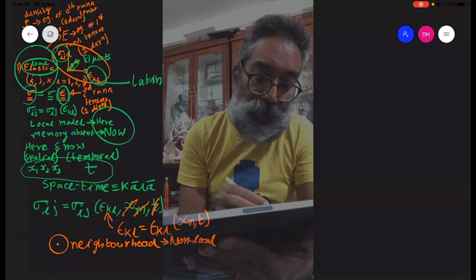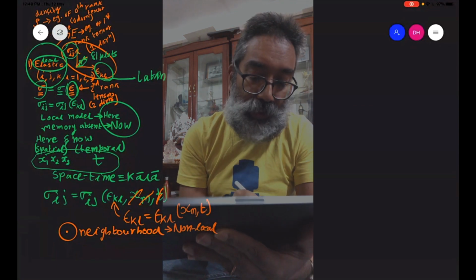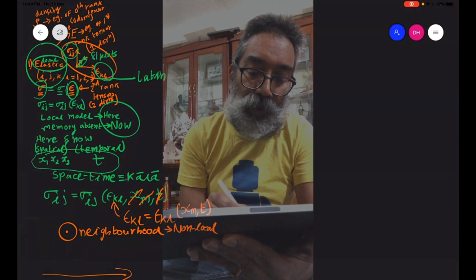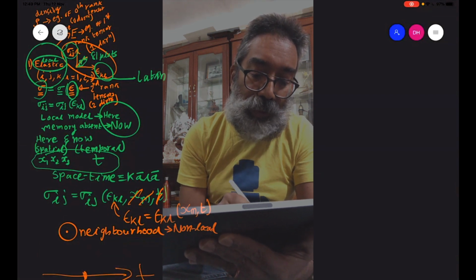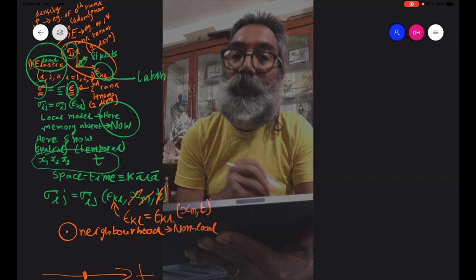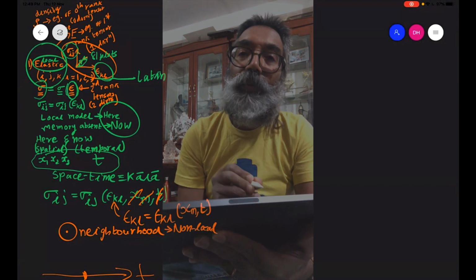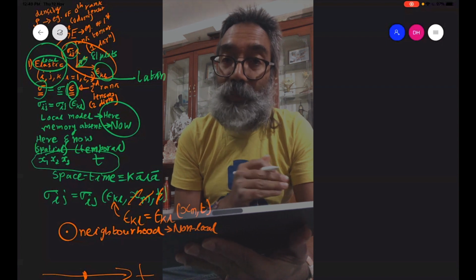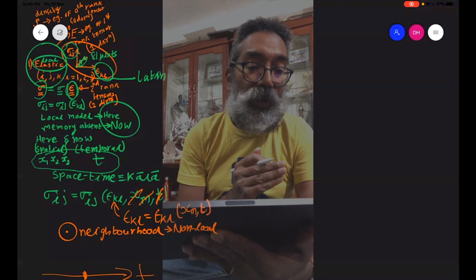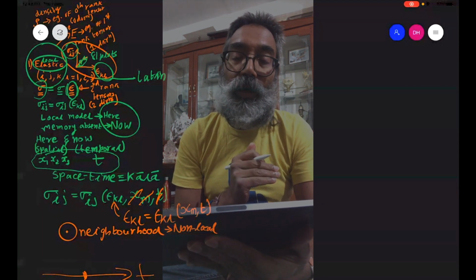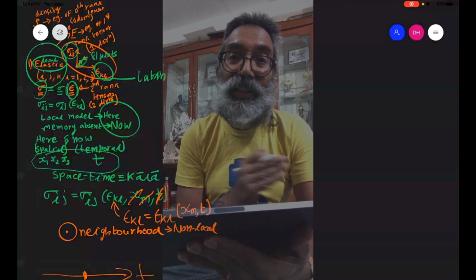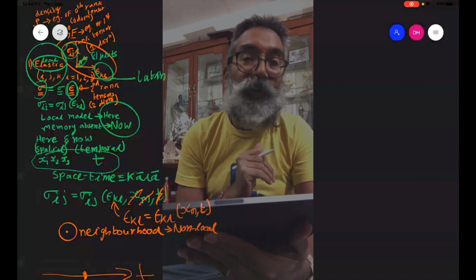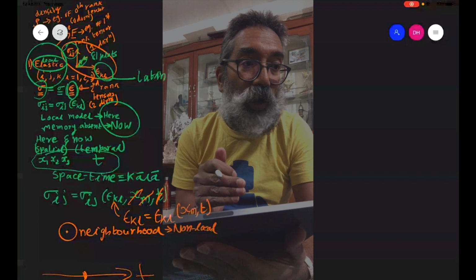We are also saying that in the sense of time, it is dependent only on what is happening at this particular instant, because what had happened before, for example, if it is a creep kind of loading, could have reduced its properties. What Vignesh pointed out in terms of an SN curve, if it has gone through a few fatigue cycles, its strength could have dropped.